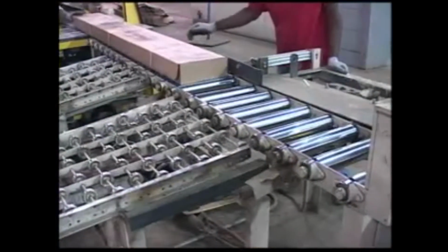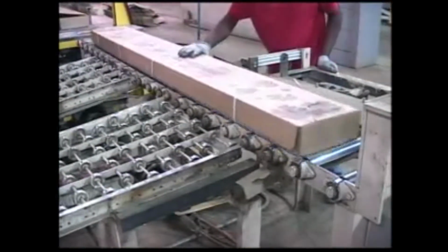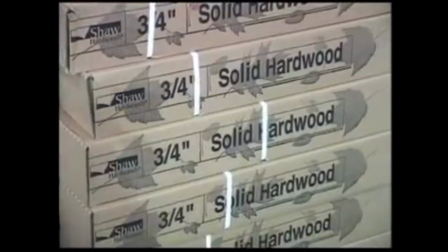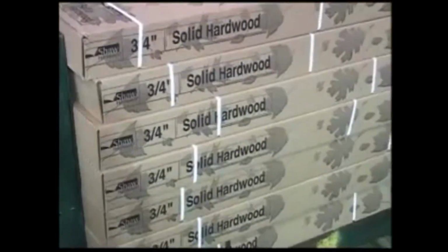Industry standards allow up to 5% of the wood in each carton to be of a lesser grade than the entire carton. This means it will include a few boards with large knots, mineral streaks, or discolorations. Also splinters, cracks, bows, thin or thick areas, wormholes, or finish imperfections, just to name a few. An average carton of 2¼ inches solid strip flooring can contain the equivalent of a 5-foot board that will be unusable.